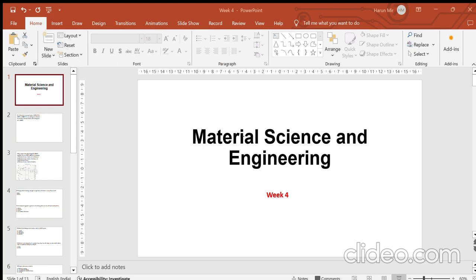Now you can find the mass fraction of alpha and beta based on this lever rule. So this fraction will give you alpha and this fraction will give you beta utilizing this value. So alpha will be equal to 91.2 minus 25, over the overall length of the lever, that is 91.2 minus 8. So this is your alpha. If you calculate, what is the weight fraction of your alpha? You can write this as the weight fraction of alpha.